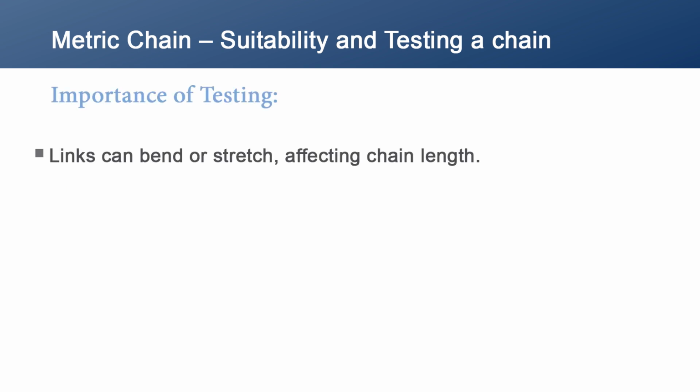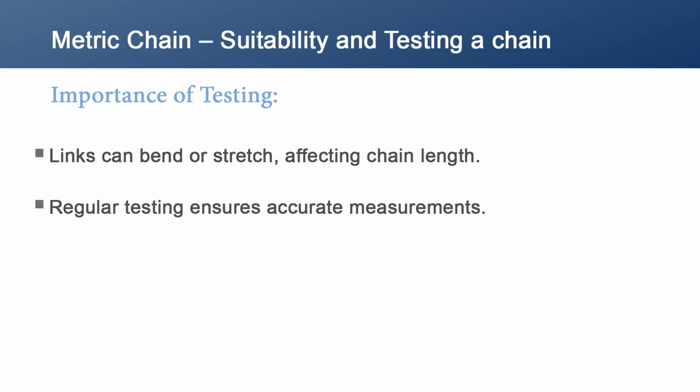And with this chain, over time, the links of the chain might bend, shortening its length, or they might stretch, lengthening it. You need to check the chain's length before you start your day's work and frequently after to ensure accurate measurement.